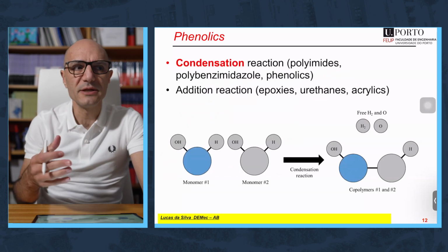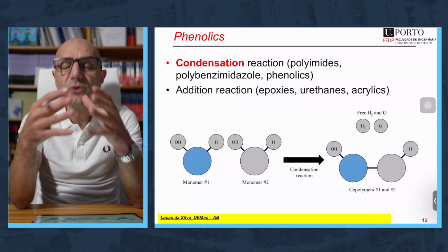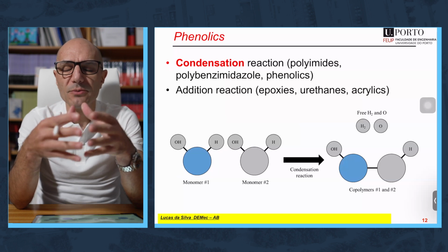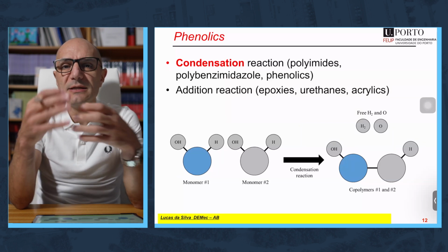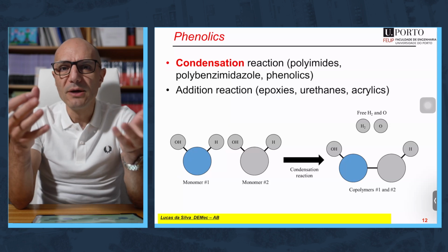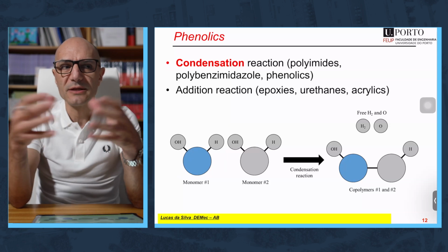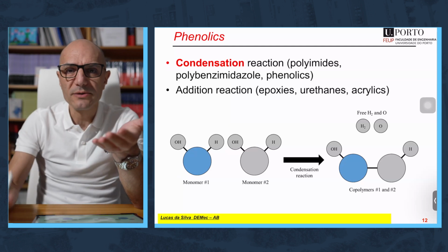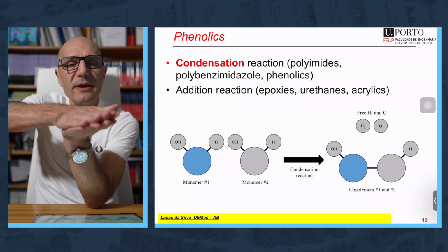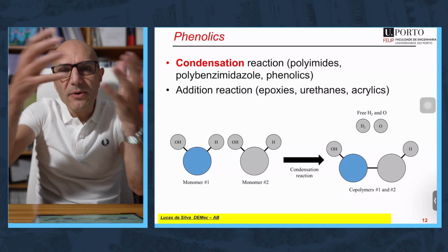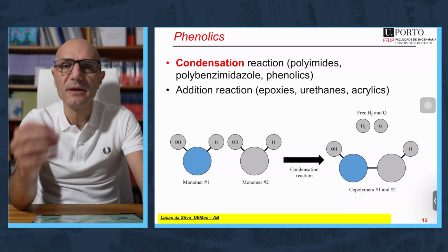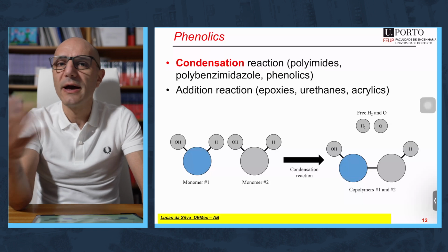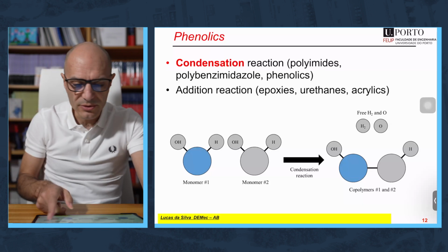What's the thing about the condensation? Why adhesives that cure by condensation need pressure? That's because during that chemical reaction by condensation, there is a release of a water molecule, and because the cure is done at high temperature, the water would expand, it would be vapor, and this would provoke porosity in the adhesive. So to counteract that effect, you really need to apply a lot of pressure so that the vapor does not expand. That's why phenolics typically really need high pressure. Epoxies, for example, they don't cure by condensation. They don't need a high pressure, just enough pressure to join the two components together.